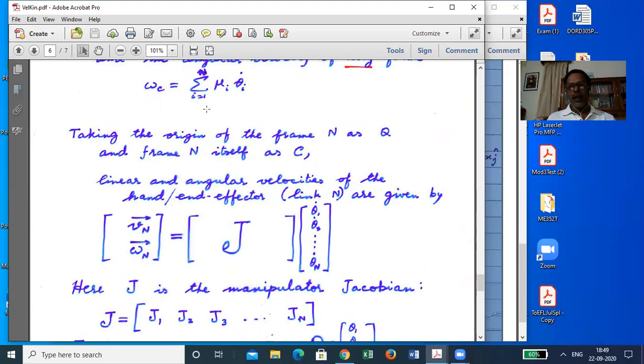And linear combinations like that can be organized in this matrix vector form, where the coefficients of the linear combinations or partial derivatives for that matter appear in this matrix, which is the Jacobian of the manipulator, or alternatively you can say Jacobian of the position mapping. So you call this matrix the manipulator Jacobian.